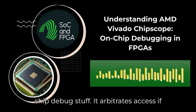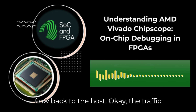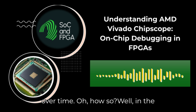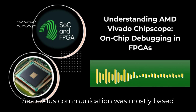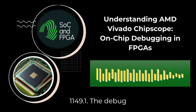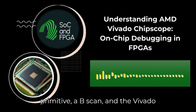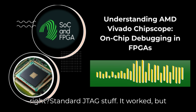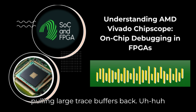It arbitrates access if you have multiple debug cores, like multiple ILAs, and it manages the data flow back to the host. Okay, the traffic controller? Kinda, yeah. And the architecture of this communication path has actually evolved quite significantly over time. Oh, how so? Well, in the pre-Versal era, so 7 Series FPGAs, UltraScale+, communication was mostly based on the device's standard JTAG port, i.e. 1149.1. The Debug Hub connected to a boundary scan primitive, a BSCAN, and the Vivado hardware manager sent low-level JTAG sequences over the programming cable. Right, standard JTAG stuff. It worked, but JTAG is relatively slow, especially for pulling large trace buffers back.